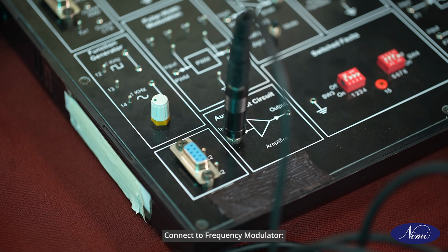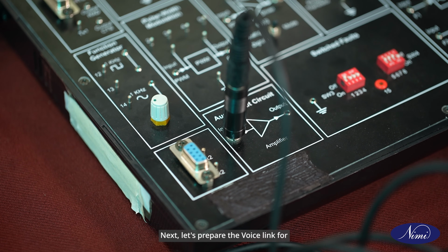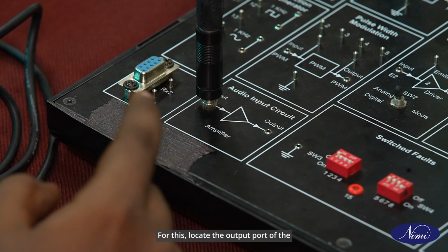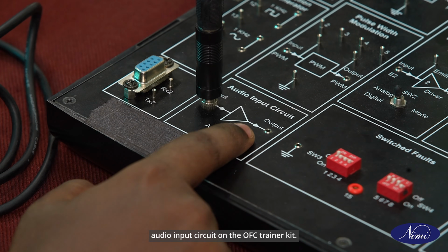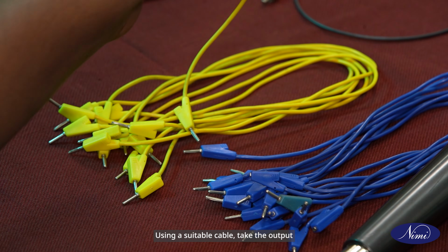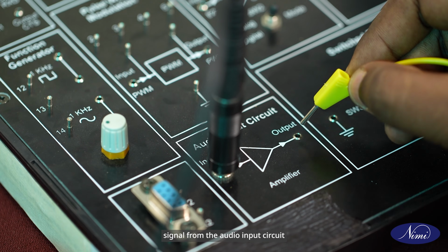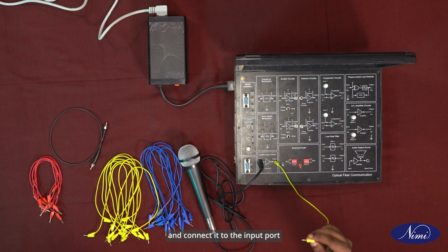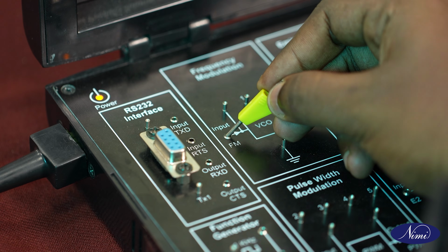Connect to frequency modulator. Next, let's prepare the voice link for modulation by connecting it to the frequency modulator. For this, locate the output port of the audio input circuit on the OFC Trainer Kit. Using a suitable cable, take the output signal from the audio input circuit and connect it to the input port of the frequency modulator.